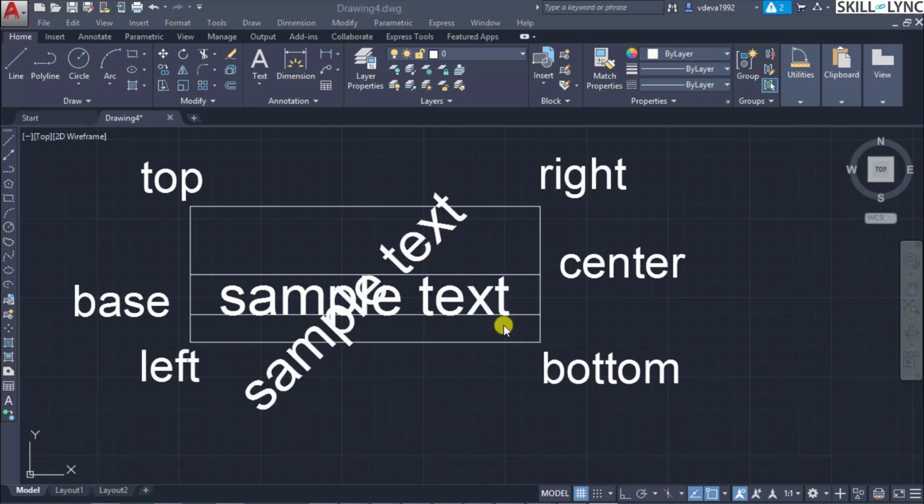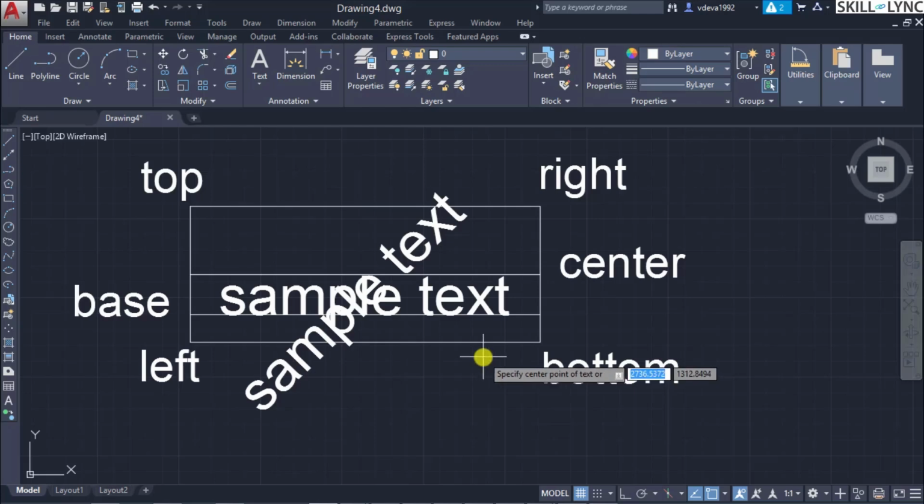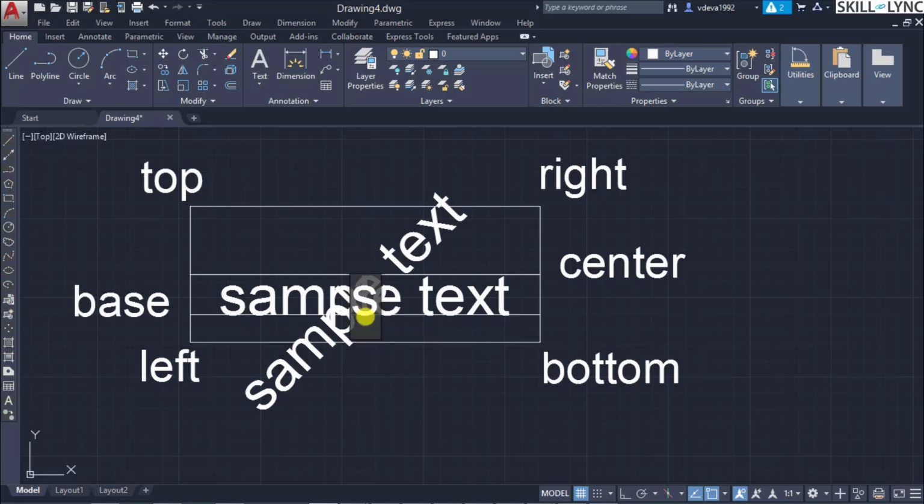So in this rotate command we can have one more variant. Suppose if you want to have the text in an upside down manner, you can affect that by specifying a rotate of 180 degrees. So let us use this text command again, and let us overwrite on the same point to see how it affects, and the text height is same, and rotation let us specify as 180 and type in sample text.